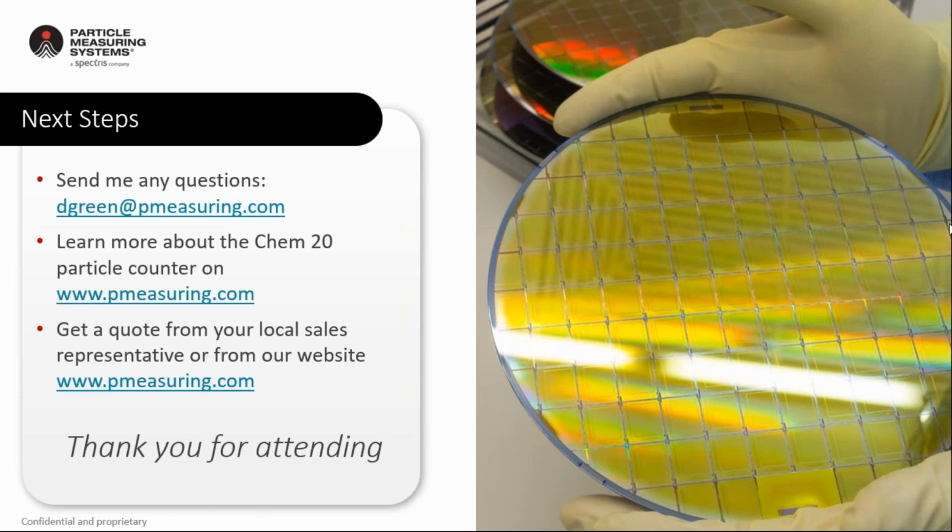And then finally, Dwight, for you, if most fluids have a particle size distribution, then why do we think monitoring at 20 nanometers is so important? Can we just monitor at a larger size and extrapolate to what the particle levels may be at smaller sizes? Yeah, that's something that's been done in the past when there was nothing available down at 20 nanometers, and many of the chemicals were being monitored at 30, 40, or 60 nanometers or something like that. And so they would try to extrapolate down.